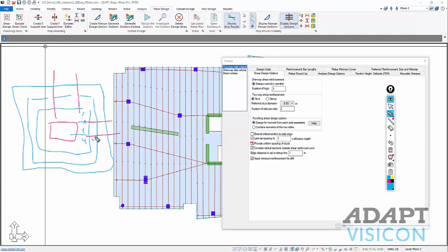This might be L2, L3, and so you might get variances in the number of studs and the spacing between layers, just depending on rounding and the program's mechanism for designing the studs within each layer. And that might lead into a design where you need, maybe studs spaced at 2 inches, and then 2.25, and then 2.25, and then maybe 2 again, depending on rounding. So this is a very specific outcome of the reinforcement.